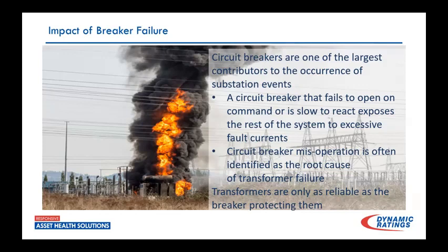So around 3 or 4 years before I left, and I saw these outage numbers starting to go up, we were seeing a lot of breaker fails on our distribution side. And they were breakers that I actually had pretty good tests for. So I thought, well, we need to come up with another way to do this. I was introduced via a friend to the first trip testing, and we started going into that and finding that we had a lot of breakers that I was getting good timing from timing and travel tests that were very, very slow on that initial operation.